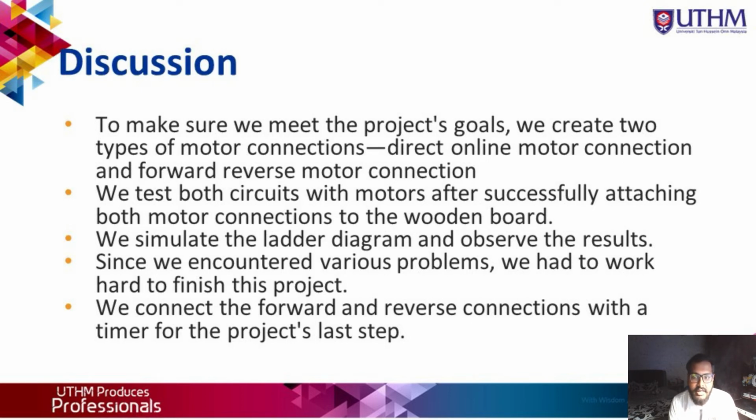As we move forward with our project, the ladder diagram is built in CX-Programmer. Afterwards, we move the program to a PLC because the lab does not have enough PLC units. So our group used a PLC module for this project. Next, we simulate the ladder diagram and observe the result. Before converting the manual operation to a PLC program, we remove the stop and start buttons.